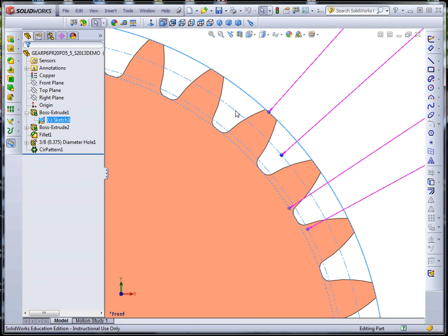This distance from the pitch circle to the dedendum circle is 1.25 over P. And then this other circle here, again, the circles that you could actually see or measure on the gear are the addendum circle where the top land is and the dedendum circle where the bottom land is. You can't see the pitch circle and you can't see the base circle.